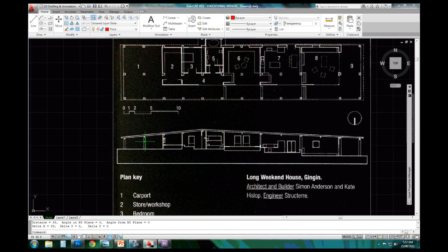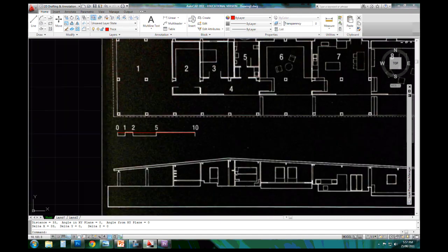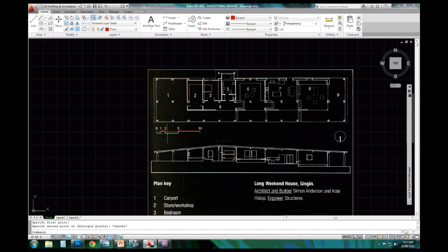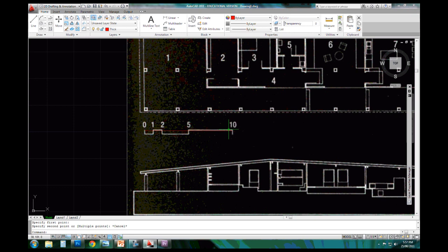You go through and you select referential, then you can scale based on a line that you draw, which was shown in technical lecture number 3. Otherwise, you can calculate the scale factor mathematically and scale the line or the object up to the new size that you want. So we want this line to represent 10 meters or 10,000 millimeters. At the moment in model space, it's representing 33 millimeters.